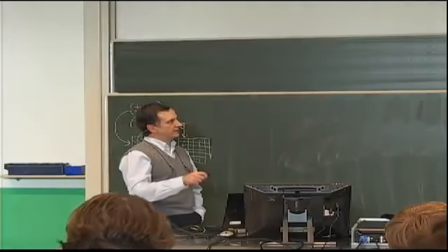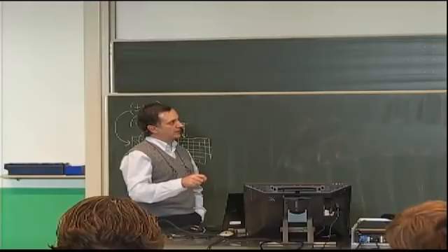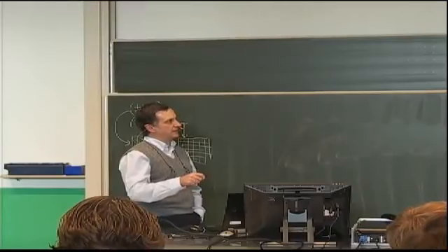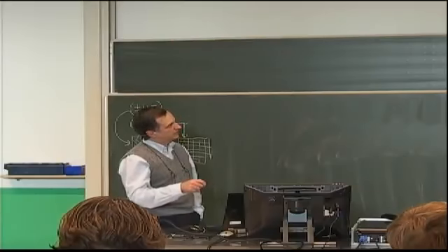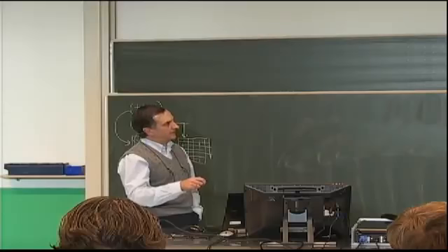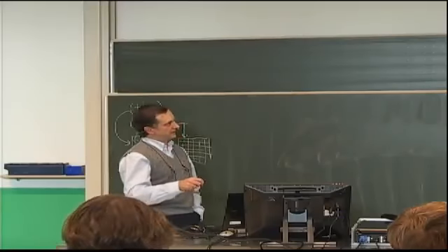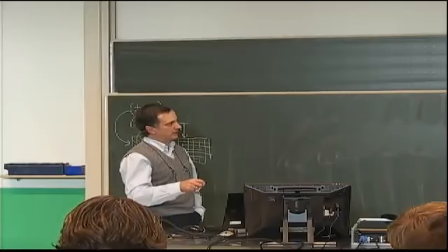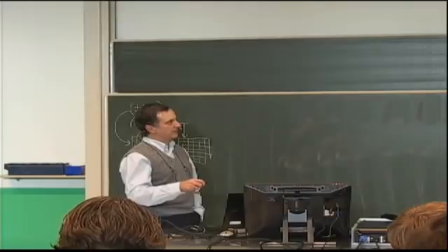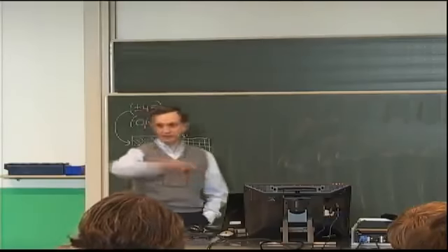is shown here, multiply each term by the orthogonal function. So wherever I have a sine m pi x over a, I'll multiply by sine p pi x over a, where p now is an integer. And similarly for the y dependence, I will have my original sine n pi y over b, but I also add my sine q pi y over b. I multiply that, and I integrate over the entire plate.